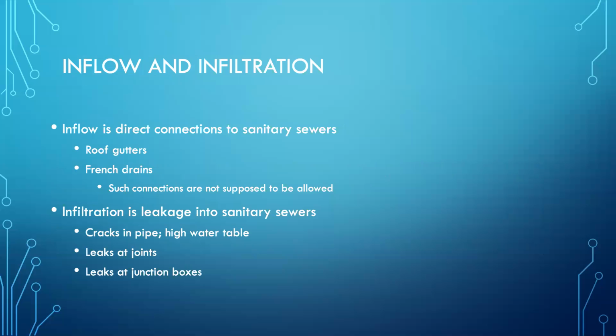And so now we'll close up with the definitions of inflow and infiltration. Inflow is defined as direct connections to sanitary sewers, and we'll look at some pictures of that in a second. And infiltration is leakage into sanitary sewers. So the key word here is infiltration is water that gets into the system because of leaks. So it's not supposed to get in. Inflow is water that gets into the system because there's a direct